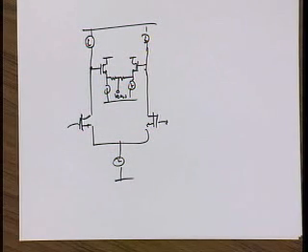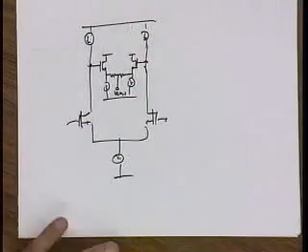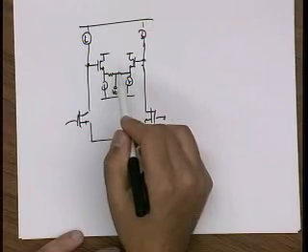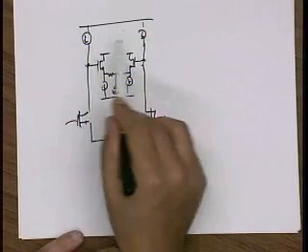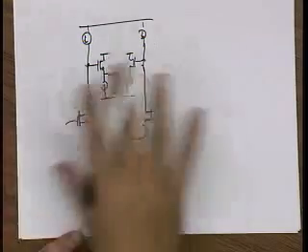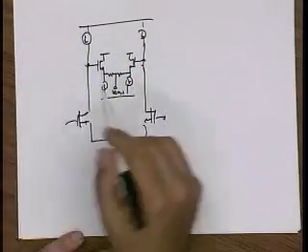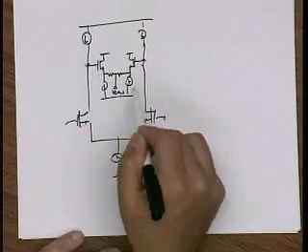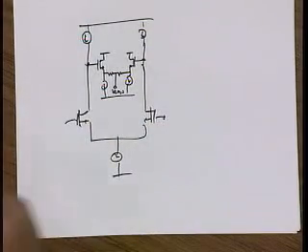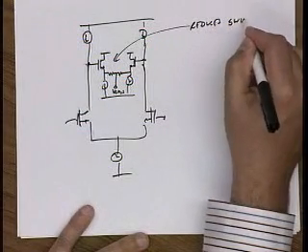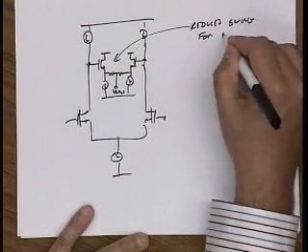You lose the threshold voltage, but it depends on how much headroom you have available. Yeah, you're absolutely right. It works, but it only works over a limited range, right? Before, I had gone to great pains to make my current mirror as high swing as possible, right? If I've designed the circuit, everything to get a really high swing, now I find out that, oh, I can't get that swing. I'm limited now by this circuitry here. So this reduces the swing for the entire amplifier.